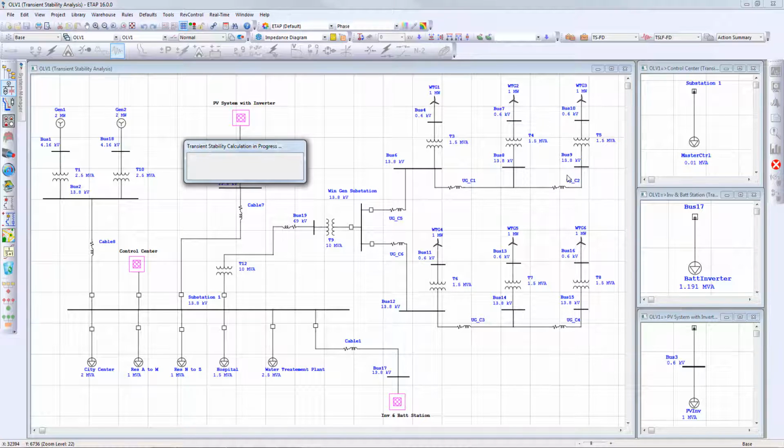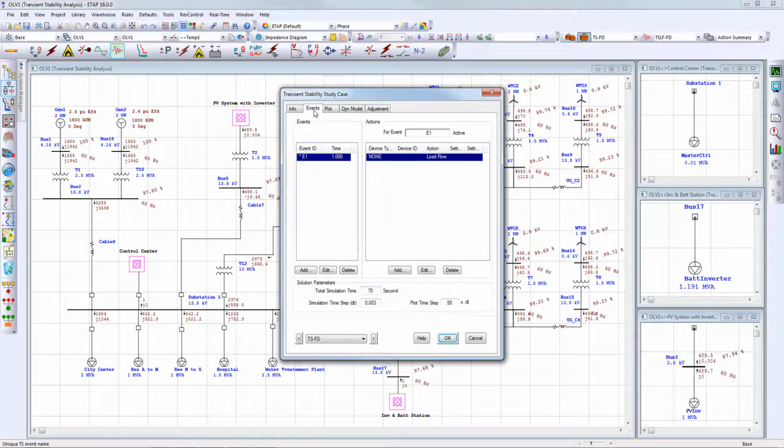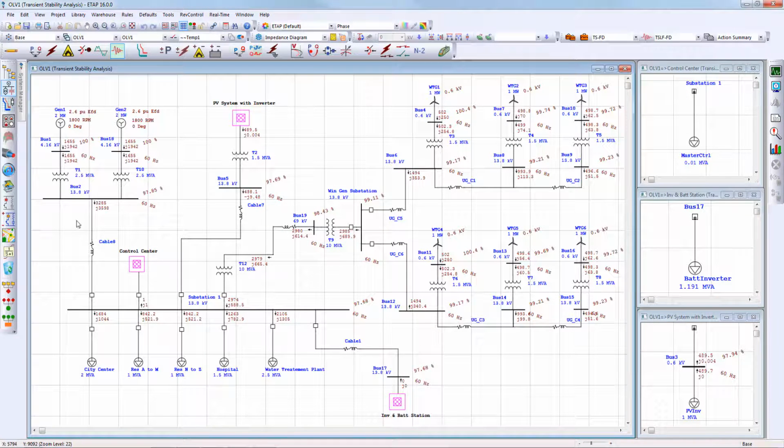The go-to blocks are a tremendous enhancement to ETAP 16 because they open up different plant level types of simulations where we can implement automatic generation control, microgrid, or grid interconnection studies. As we will be able to see in this simulation, what we just executed is in essence a simple low flow event. There is nothing indicated through the study case. Everything in the simulation is being controlled by the master controller inside of this UDM element in the control center.